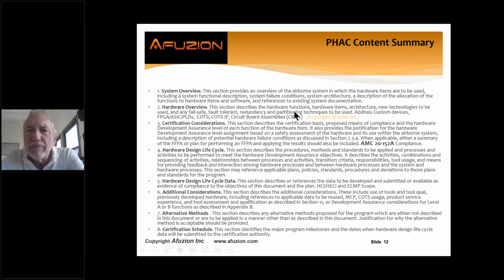Well, real briefly, we want that PHAC, and this applies to PSAC obliquely, to summarize the system. What are you building? What's a quick half-page functional description? What are the components, subsystems? How could each of those fail? What's the architecture? How much redundancy, monitoring? What communication channels are we going to have? Which functionality is allocated to hardware versus software? And are we referencing system documentation? Because if we don't have system documentation, we don't know how many floors are in the building. Why are we submitting building plans if we don't know where the elevator is?